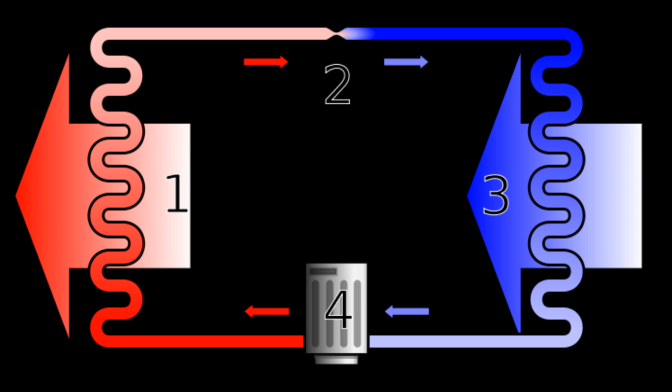And if you remove it, the temperature will be reduced even without taking out any heat energy, and you can then again build a cycle: place it in a magnetic field so it gets warmer, sink out the heat, remove it from the magnetic field, pull heat in, and then you have a cycle like the old pressure-based or condensation-based heat pump.